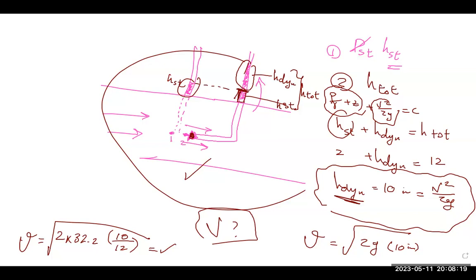This is a device. We don't change the shape of the device. It is a device used to calculate the velocity, so we make and manufacture it as it is. One pipe is a long straight pipe, and the other pipe is L shape to create, or to obtain, a stagnation.